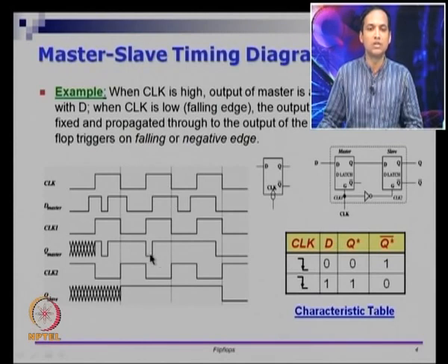It goes to 0 because when CLK1 came in, D master is 0, it starts with that, and then it goes to 1 at some point, and stays at 1 till the clock goes off. When CLK1 goes off, again there are changes here, it changes from 1 to 0 to 1. However, those changes are not seen in Q of the master. And finally, when the third clock tick comes on, D master is already 1, it goes down to 0 once, and that is captured in Q master, right.